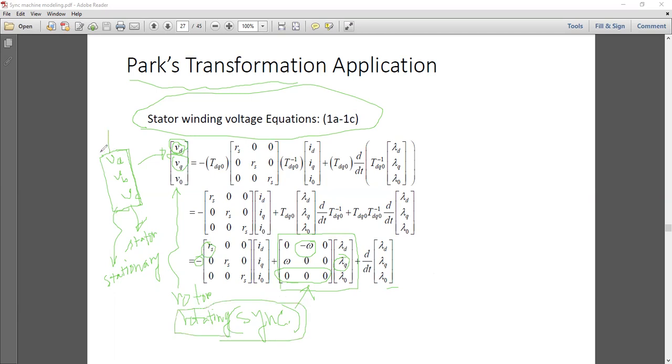Okay, we don't have like these VA, VB, VC, which are some sine function of omega t. Okay, sine omega t plus theta, sine omega t minus theta, some sort of sine or cosine. So they are time dependent. Okay, in the stationary frame, these VA, VB, and VC are time dependent. Whereas in the rotating frame, these VD, VQ, and V0 would give me simply some DC values.